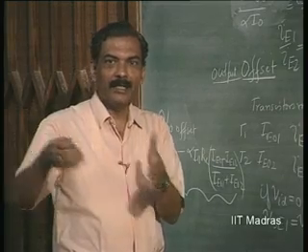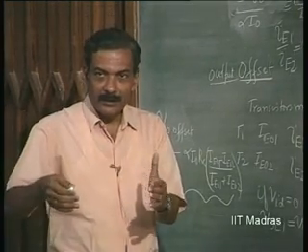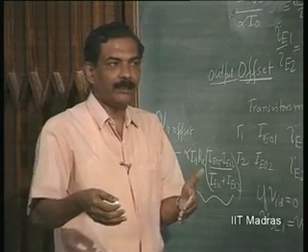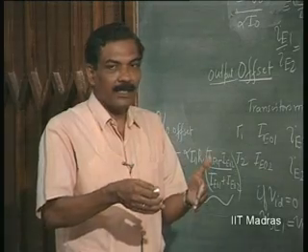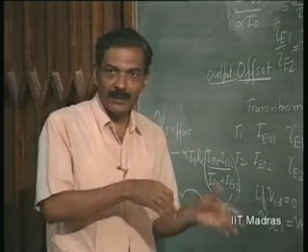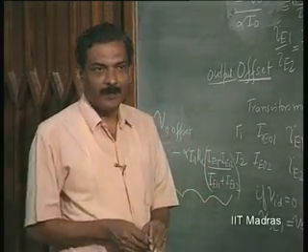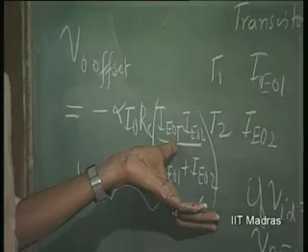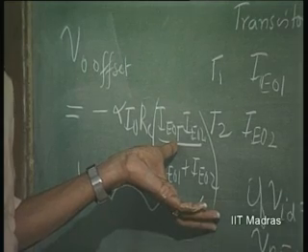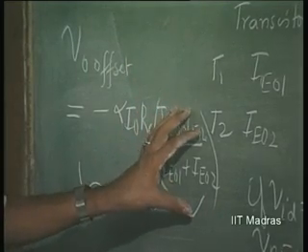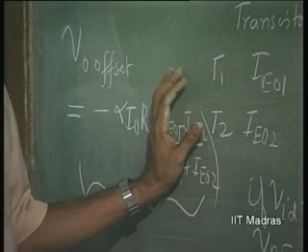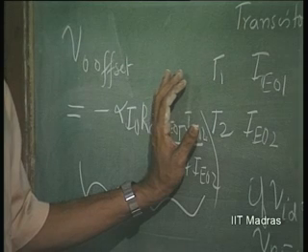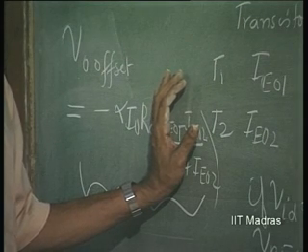This is adding to the noise. This itself is now generating some amount of noise. Particularly, this is of great nuisance in the case of a low frequency amplifier, where the signal also changes very slowly with respect to time. We cannot separate this out from the signal, so it interferes with the signal. Therefore, in a good amplifier, we must make this as close to 0 as possible. Not only that, it should not further drift with respect to time. These are two important things.